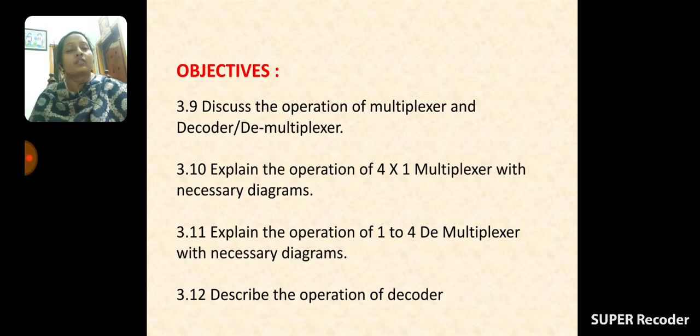In the parallel adder, many full adders are used. In each stage, to add three bits at the same time, one full adder is required. So if n bits are added, n full adders are required. In this way it adds multiple bits at the same time with high speed, but with high cost, and the circuit becomes complex.